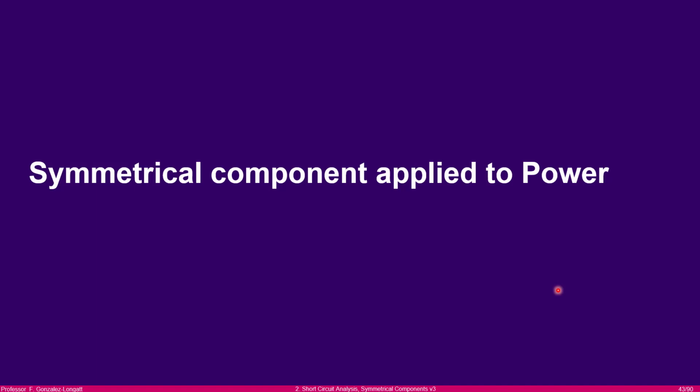Well, now you have a proper understanding about the basic mathematical relationship between symmetrical and asymmetrical components, okay? Something that you must realize is that symmetrical components are similar to the per unit system. I mean, the per unit system works perfectly, makes your life easy, and is a very important tool for power system analysis.